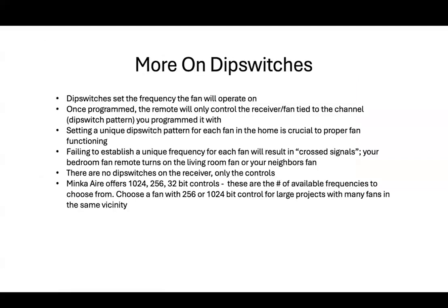More on dip switches. A few more points to remember about dip switches and programming RF-based fans. Dip switches should be set prior to programming the fan. There are only dip switches on the control, not the receiver. As mentioned previously, it is important to consider the number of fans in the same area on large projects. Minka Aire offers a variety of controls with different numbers of unique frequencies. 32-bit controls have only 32 unique channels and should not be used in situations where there are more than 32 fans in a range of 50 to 60 feet.